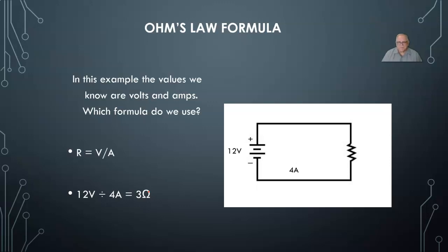Now, the place where you have probably seen this is if you have your headlights on, drive the car, pull up to a wall or garage door or some surface where you can see the lights, and then you shut the key off and you see the lights dim down a little bit. So with the car running, you'll have about 14 volts. With the car shut off, you're down closer to 12 volts. So as you lose that 1.5, 2 volts, the lights dim down even though the resistance remained relatively unchanged.